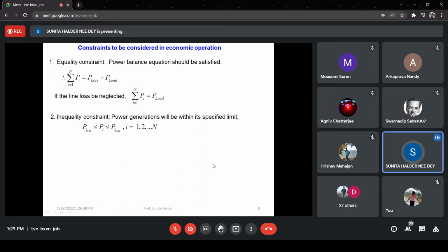So it can readily accept any loading at any time. That's why theoretically P minimum may be 0, but practically we maintain some nominal value of generation, and we do not discard the generation from the system because it takes a lot of time to make it into operation. You have learned that in your second year classes in power supply system.